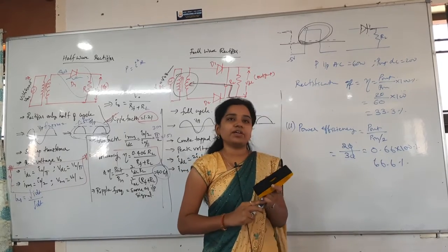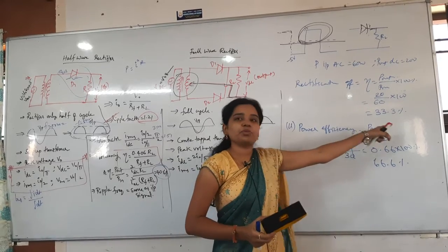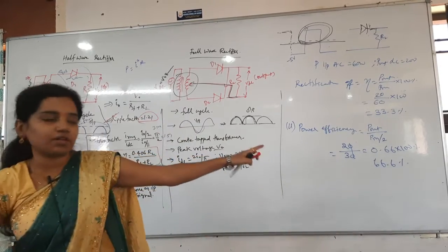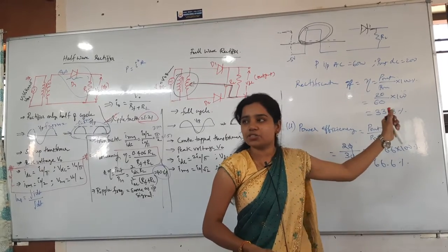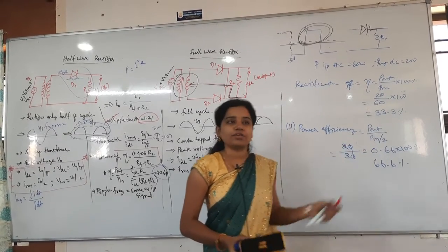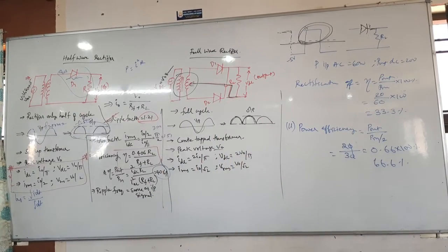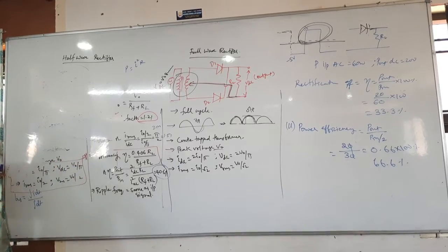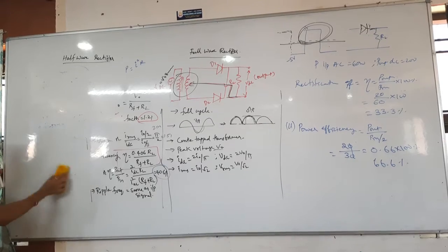Instead of a half wave rectifier, for example, if they have given a full wave rectifier, then what's your answer? Again 33.33 only. Clear? Actually, for a full wave rectifier they will not give such small values. They will give near 80, above 70 like that. That is about the half wave rectifier. Write the reason also, why we have taken P in by 2 there. What is the reason? A half wave rectifier takes only half of the signal, that's it.